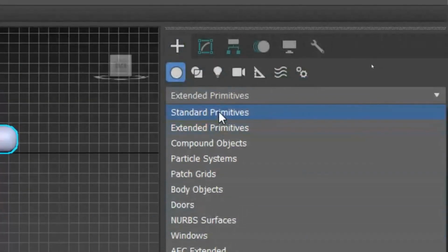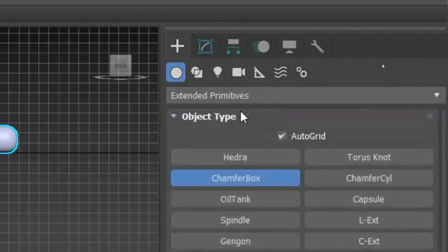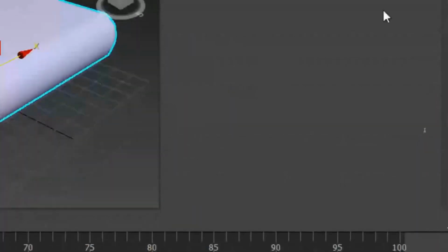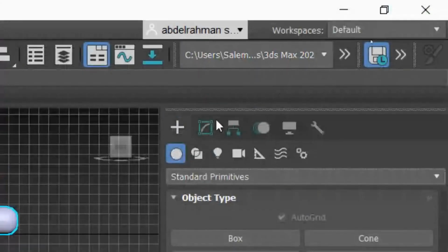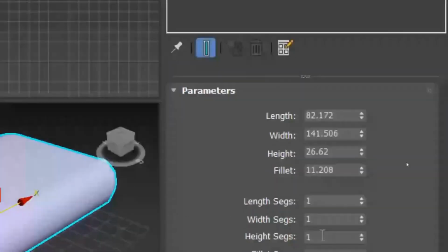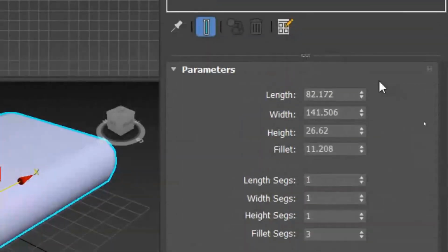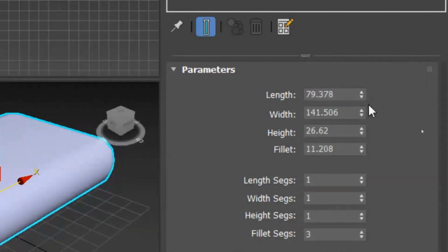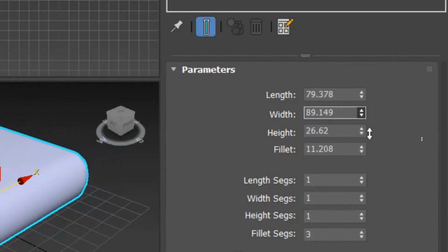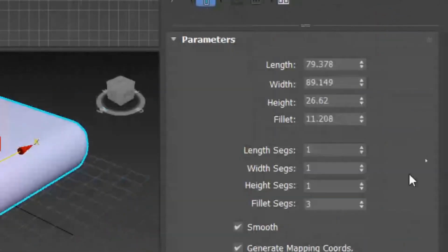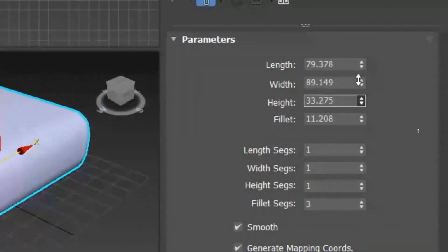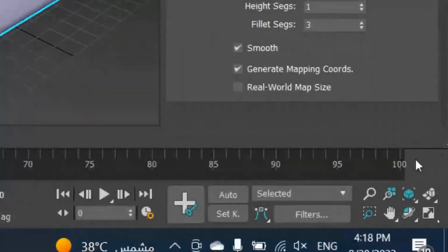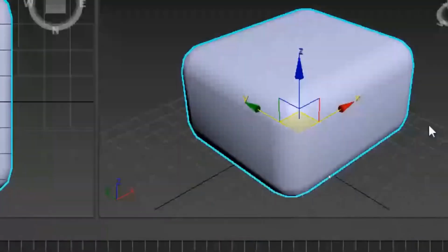If I increase the height, let's see our lines in wireframe. It was 0, it was 1, so there's nothing to shape from above. I can remove the cover. In modeling here, I just need to remove the cover, unlike my chair from yesterday where I used bevel and extrude. We have our box. You can see how the size adjusts. Make it smaller or larger, any width you want. This is good but not shapeable. Just remove the cover, unlike yesterday's chair with bevel and extrude.